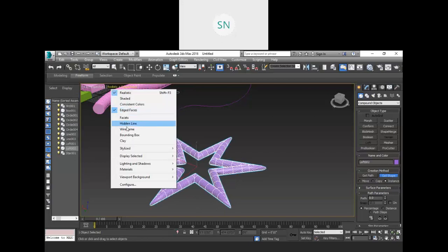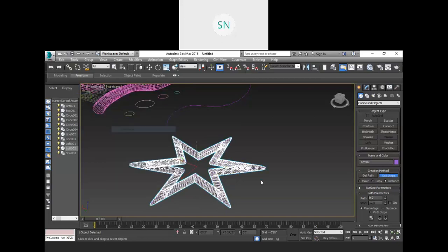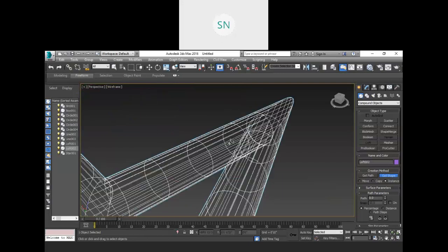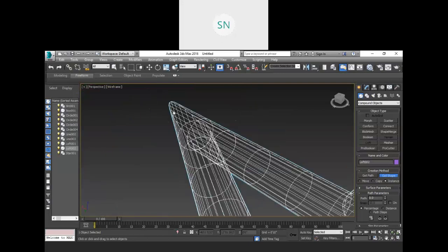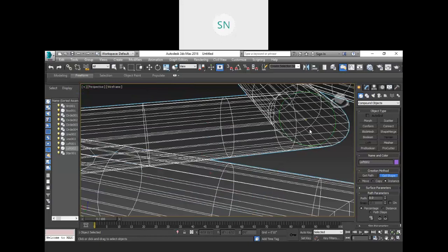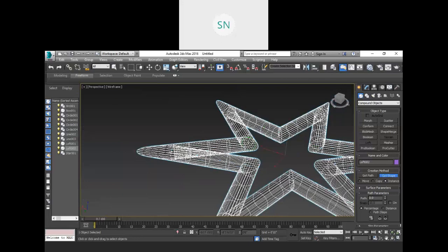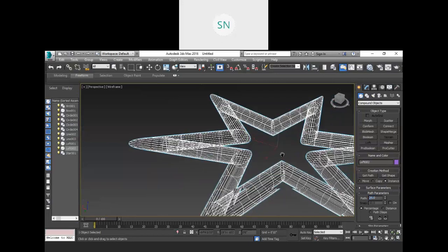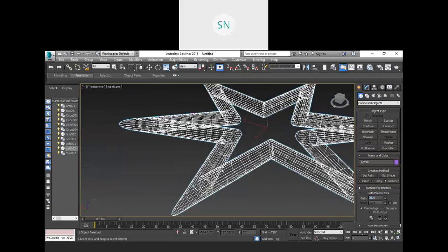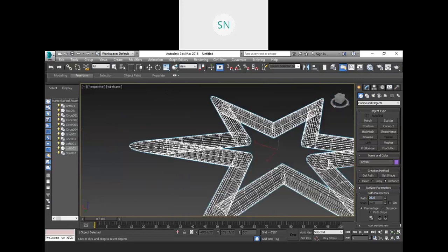Now you have to find the beginning position. So turn it on the wireframe and find where you have your beginning. Yes, it is here. See, we have the yellow cross. So this first shape is over here. Now the second shape, type a new value, let's say 25%. So that yellow cross may be on this side or that side. That we have to find.